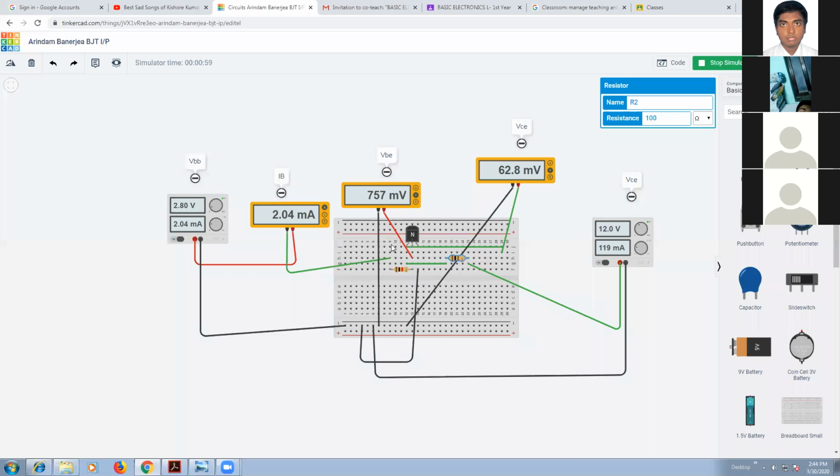So now you can see here in Tinkercad. You can tally with this circuit. Here you can see this is the NPN transistor. As usual, if you keep the flat surface towards your side, then you can see the leftmost one is the collector. Yes, here with the cursor, this is the collector.